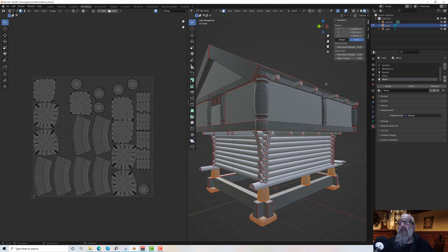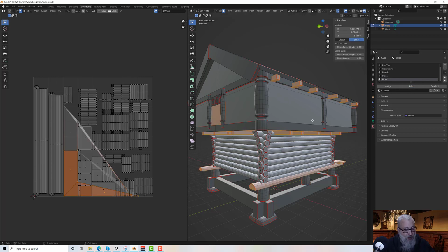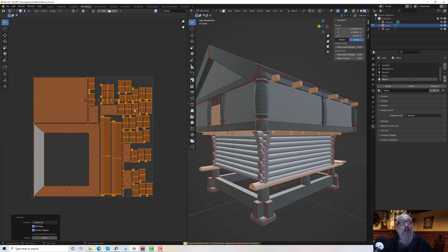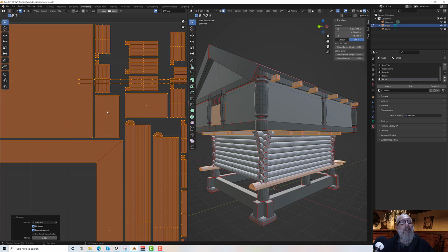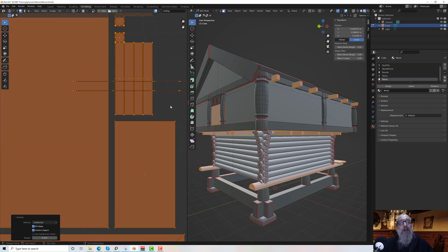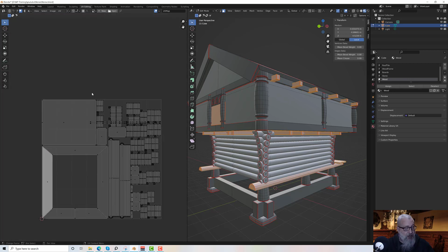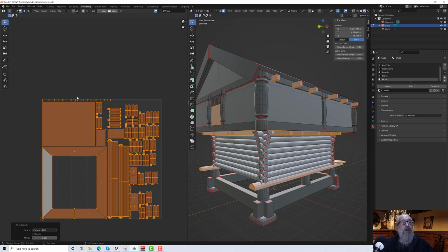And lastly, the wood. So deselect, select wood. I seem to have an issue here, so let's see if we can deal with that. So I'll press A over here, right click and unwrap. Just need an unwrap, that's fine. Let's have a look what's going on up there. What's this? Okay, so I'll press A, UV and pack. Where's pack gone? There it is.